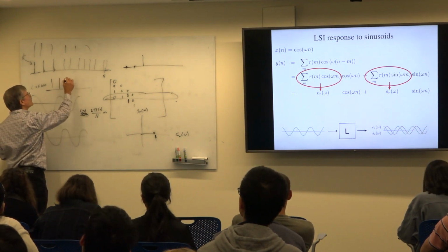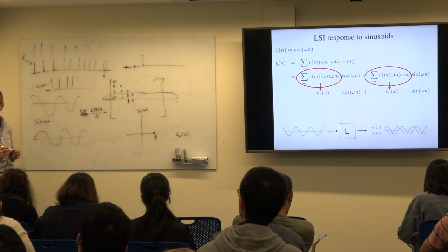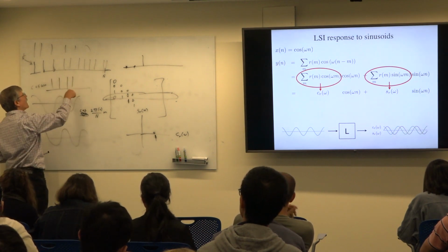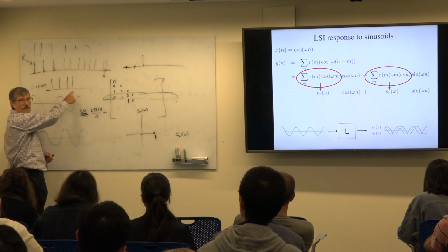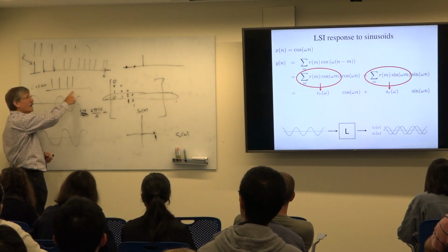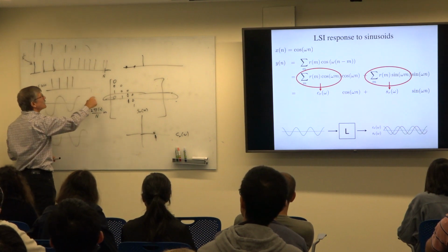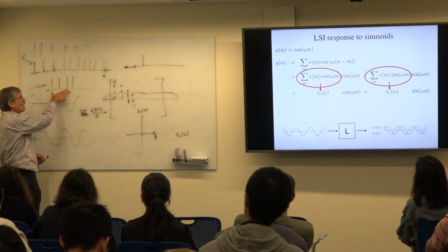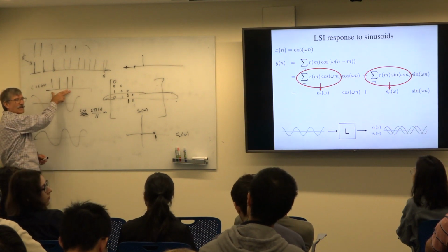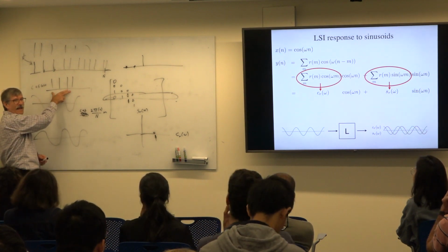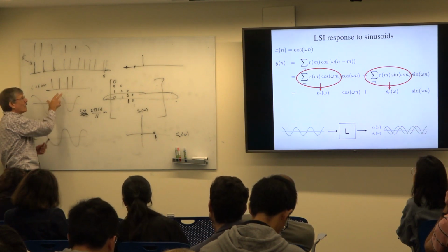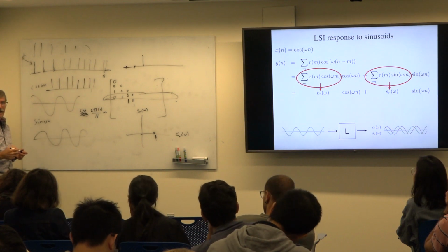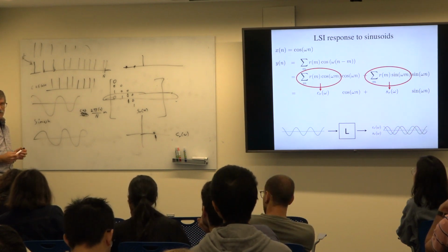When I go in between, this was my averager as an impulse response. So a wiggle that's so fast that it goes up, down, dotted with this, will cancel. That's a really high frequency. A frequency that goes really slowly will get through because it'll have a non-zero dot product. And so this one will quash high frequencies, and the lower they get, the more that'll get through. The more of these I include, the fewer frequencies that get through. Okay? So that's just an example.